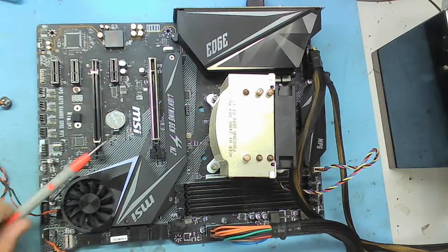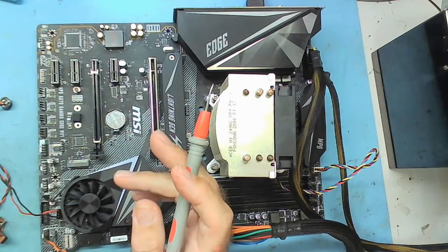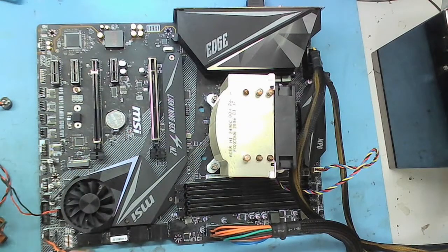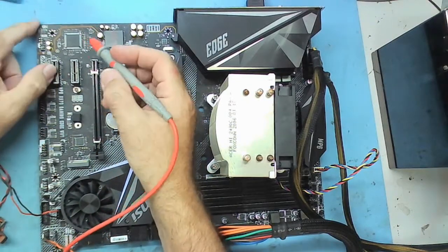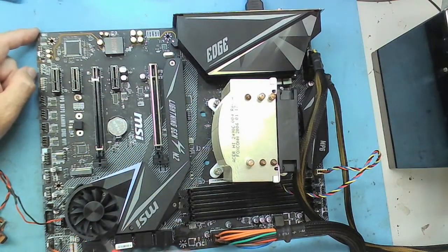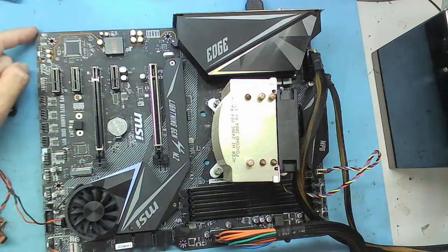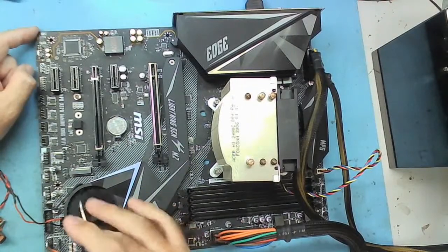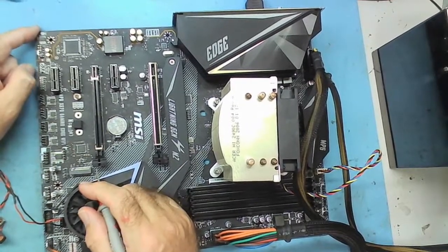You may find some chipsets that are different to that, and you have to read the chipset data sheets, but that's generally the case. So what we need to figure out first is have we got standby voltage here, and have we got standby voltage here? Because I can't see a south bridge on this. Maybe AMD don't use a south bridge. Maybe this is north and south bridge, and I know it's going to be under here because there's a fan on it. Maybe that's both on an AMD.